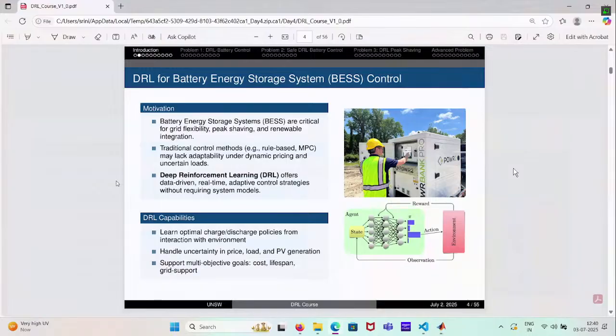It learns how to charge and discharge a battery, and it will do a good job even if the conditions around it change, even if the tariff price changes. So it will take the latest thing. The way it does it is the reward. If the reward changes, and you can change the reward dynamically, it will adapt its policy depending on the reward. I may not know anything, but I know what change in tariff prices has been there, so I can immediately change the reward. It has its policy based on the previous rewards; new rewards have come, and it has learned to deal with the new rewards and give you a different action.